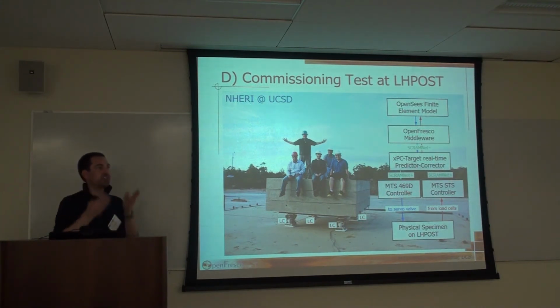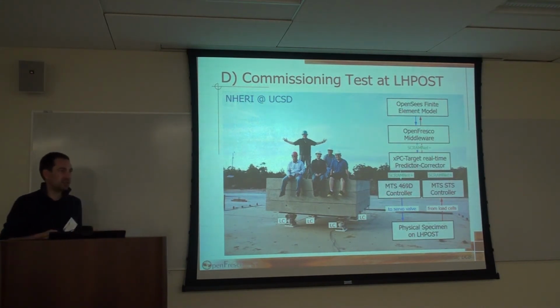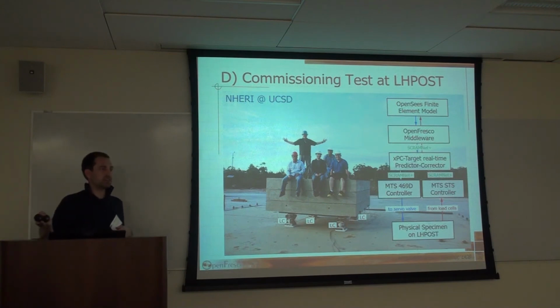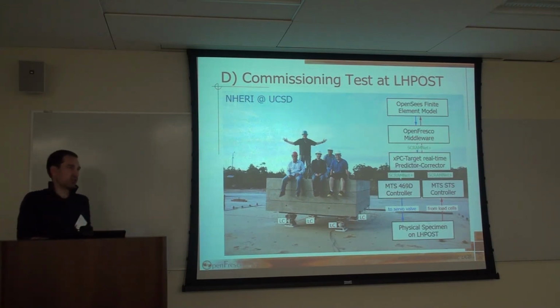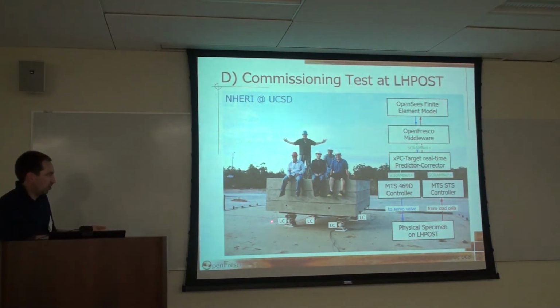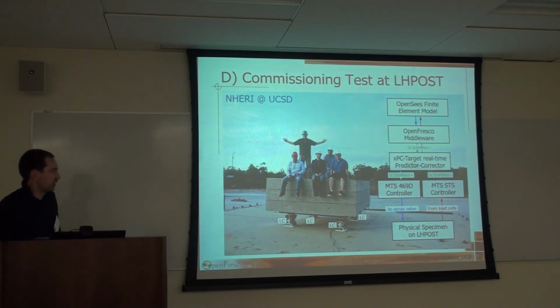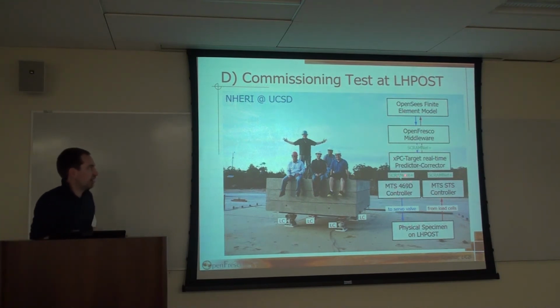Because we want to have everything synchronized perfectly, we didn't want to use a separate DAC system, because then we would have to start dealing with synchronization issues between the control system and the data acquisition system to get those load cell measurements back into the analysis model. So we have extra conditioners on our system, and we have 40 channels available, so we can easily feed all these load cell channels through the controller to get the forces back.